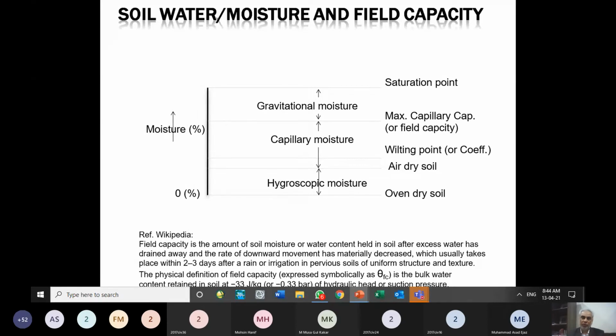When we have the water in the rivers and we supply it, we don't provide water on a demand based system. Our goal of a good irrigation system is that we should convert slowly towards a demand-based irrigation system. In the demand-based irrigation system, this is how we decide: on a daily, continuous basis, we keep the record of the soil moisture, and when the soil moisture reaches close to the wilting point, then we apply irrigation, and we apply that much irrigation which increases the moisture content to field capacity, not beyond that. That is the concept we use in sprinklers also. That is the concept we should use in a scientifically based working irrigation system.